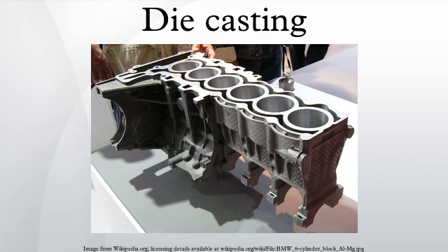Advantages and disadvantages. Advantages of die casting: excellent dimensional accuracy, and smooth cast surfaces. Thinner walls can be cast as compared to sand and permanent mold casting. Inserts can be cast in. Reduces or eliminates secondary machining operations. Rapid production rates. Casting tensile strength as high as 415 megapascals. Casting of low fluidity metals.